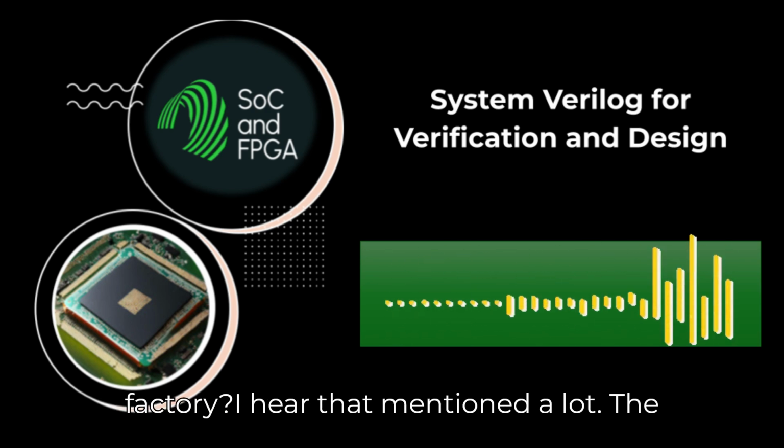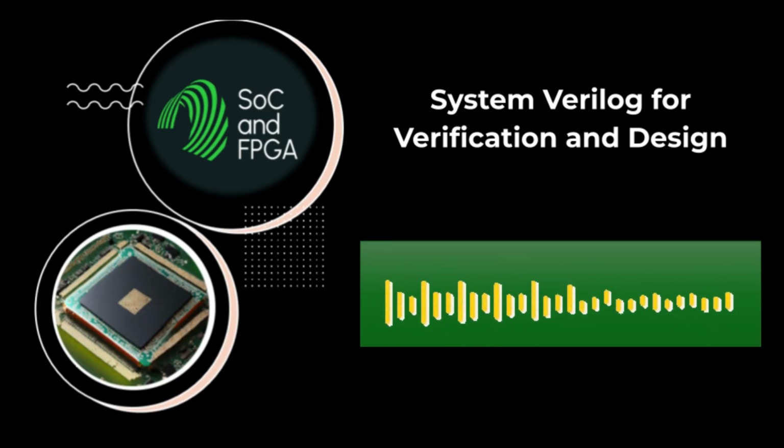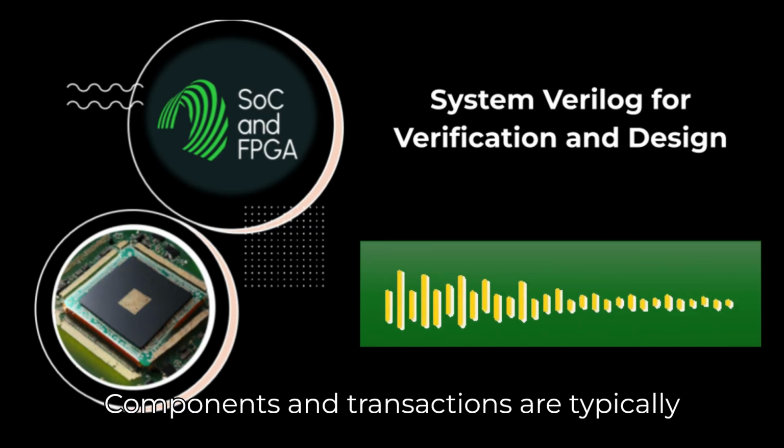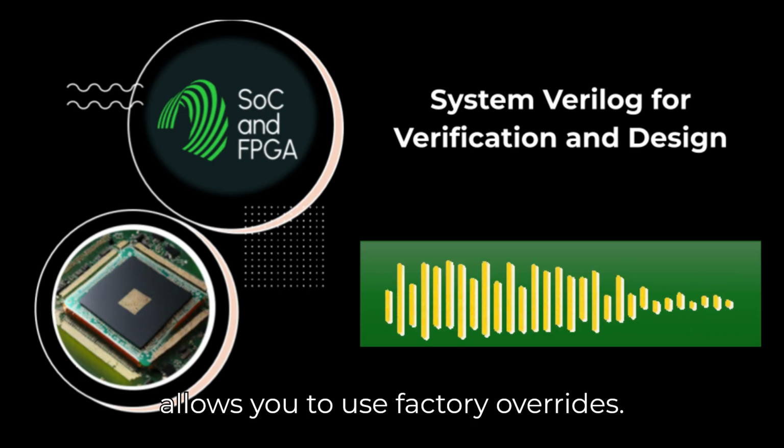What about the UVM factory? I hear that mentioned a lot. The factory is key for flexibility and reuse. Components and transactions are typically created using the factory's create method, not directly using new. This allows you to use factory overrides.